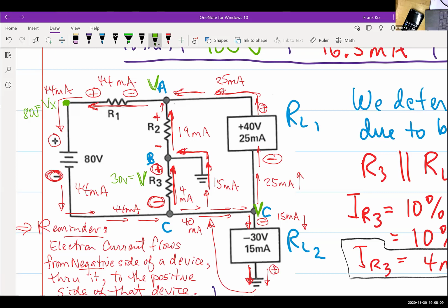If I ask you, however, for a voltage across a resistor, is there any implied position for red and black probes? No, I'm only looking for a magnitude. So this is 30 volts between here and here, and that's what you fill in on your table. You don't write negative 30 volts on your VIR table. Are we clear on that? Okay. 30 volts would be negative only at a point with respect to ground. And it is negative 30 volts from here to here, and it's also negative 30 volts from here to here.